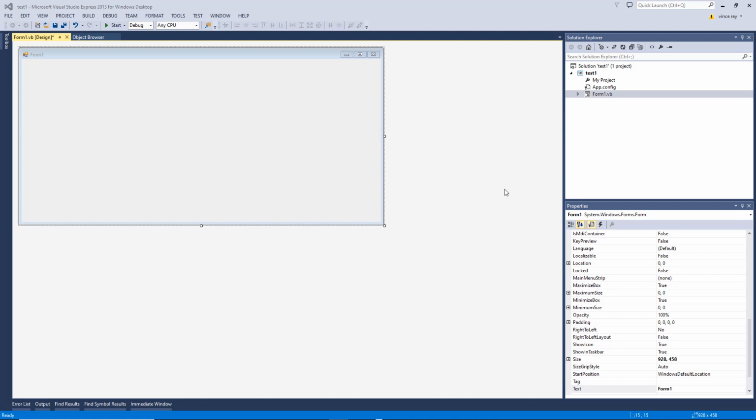That's the programming language I'm going to use today. In that example, we'll build a simple app that will do a couple of things. We'll do a calibration check, so I want to calibrate a microphone and get its sensitivity. I also want to do a frequency response measurement with THD. On top of that, I want to make a pass-fail metric to visualize whether my FRF and THD fit in some tolerance curve, right?